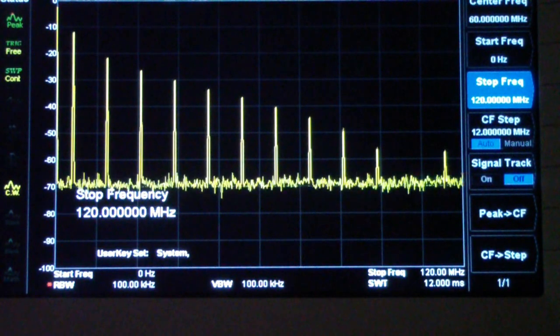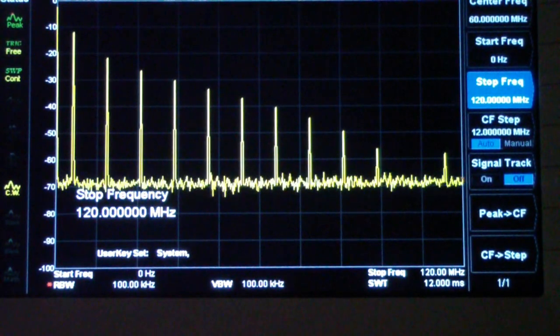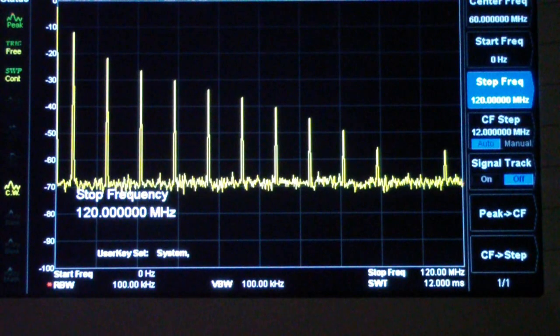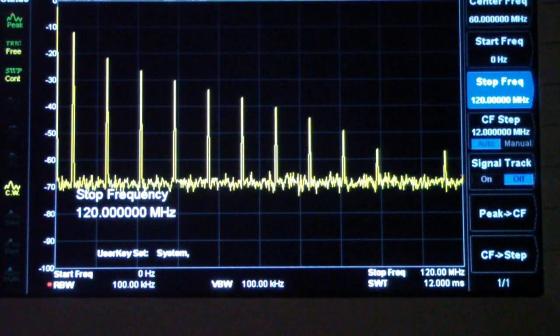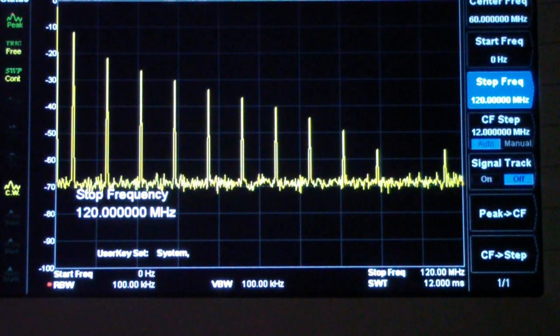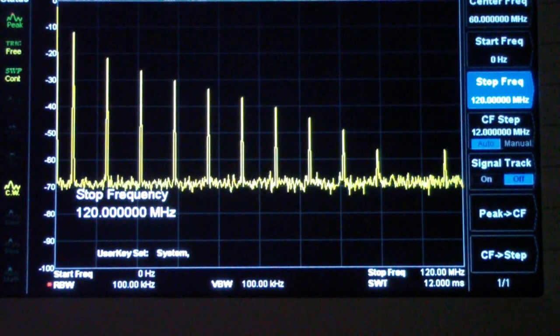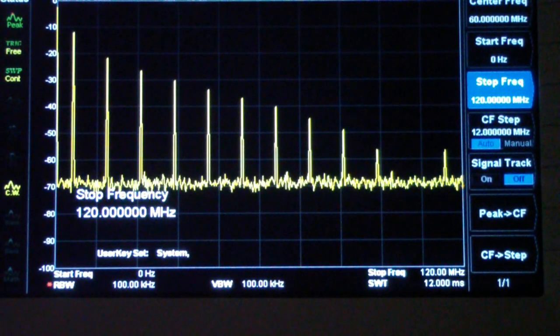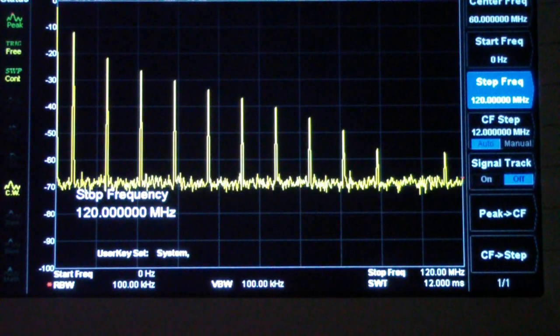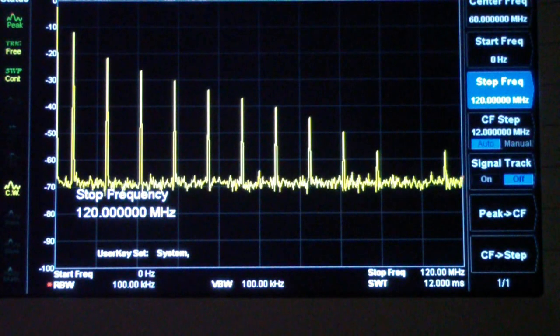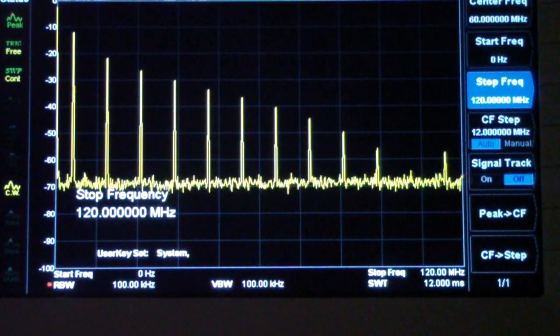The second problem is these are spaced quite a ways apart. So for example, if you have a 1 megahertz base signal, the third harmonic is going to be at 3 megahertz and so on. And often that's too far apart to be useful in looking for things like reflection